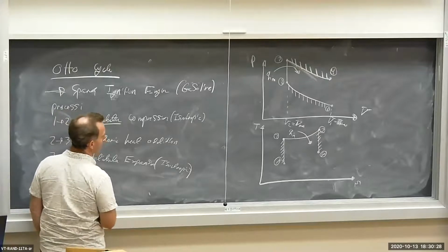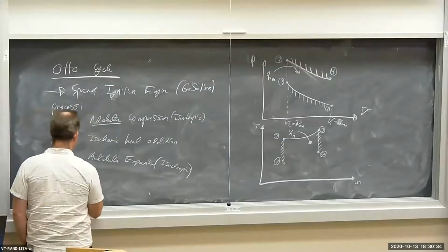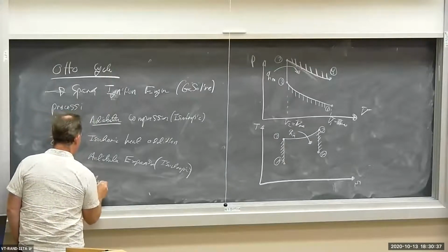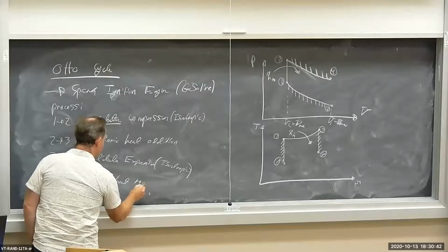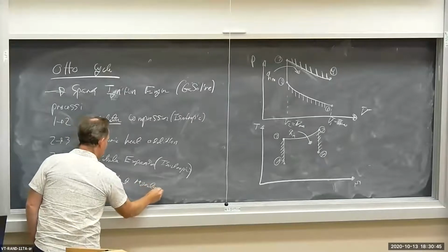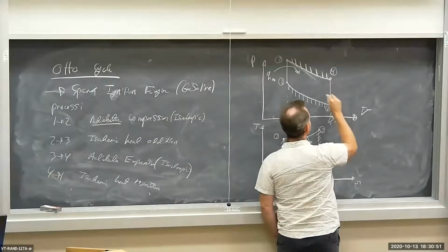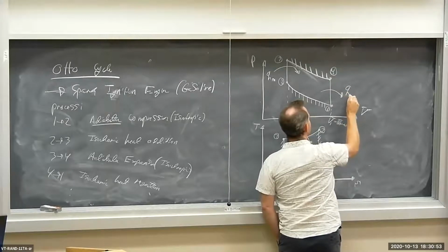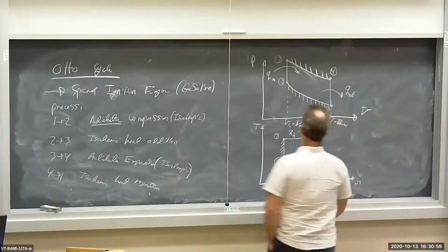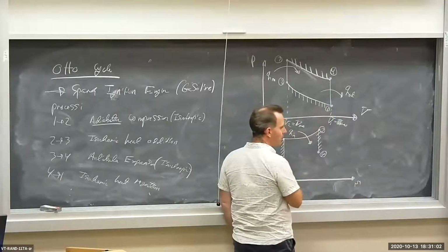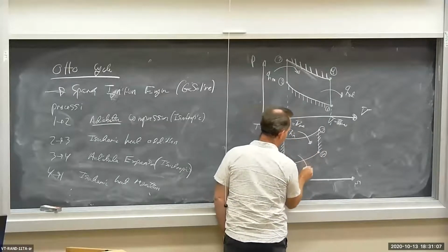We have constant volume or isochoric heat rejection. Isochoric constant volume, Q out flows from 4 to 1. Temperature falls, entropy falls, heat transfers entropy out of the system because it's flowing out. It cools down and entropy falls.